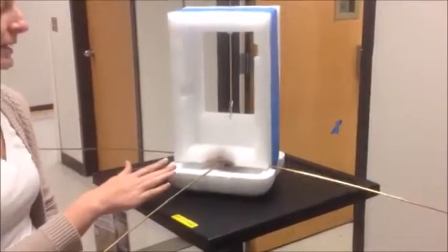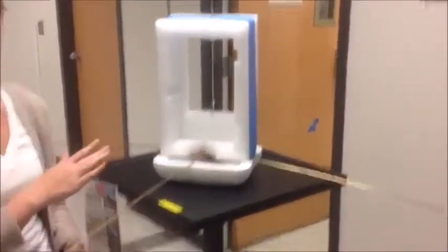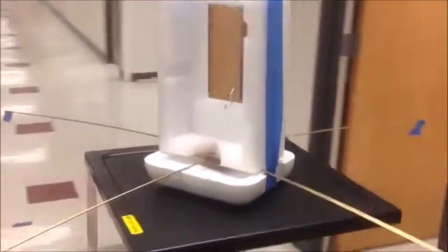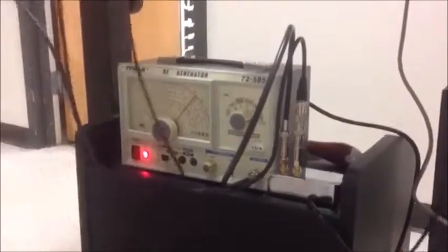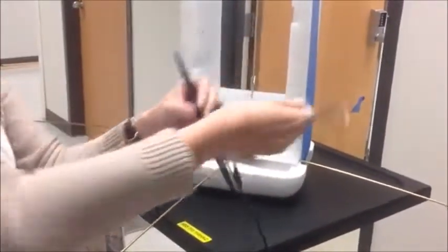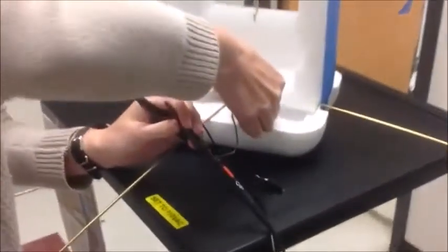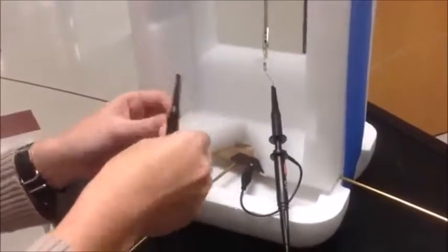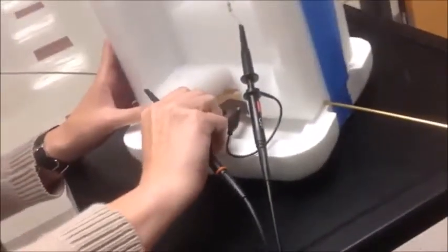This is our transmitting antenna. It is modeled after Marconi's ground antenna. I have the oscilloscope leads and our function generator down here, the high-powered function generator. And I'm going to hook up the leads to the antenna. I'm going to hook up channel 1 and channel 2 to ground, which is this plate down here. And then I'm going to hook up, after this, to the 1 kilo ohm resistor. And this one's also going to go to the 1 kilo ohm resistor into ground.